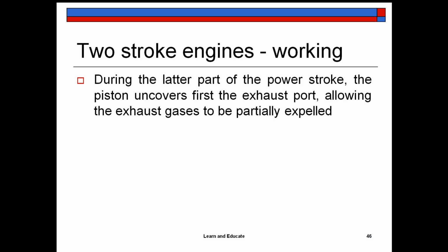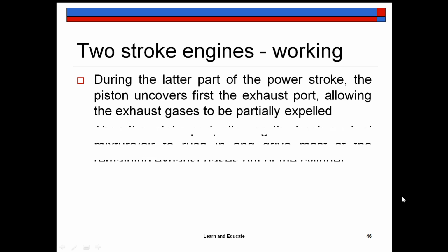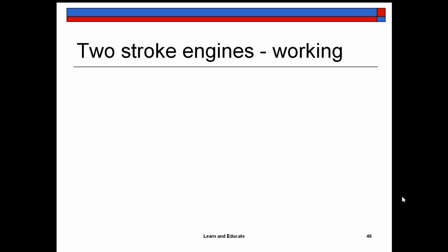So as we have discussed, during the latter part of the power stroke, when the piston is coming down from the top dead center to the bottom dead center, the piston uncovers first the exhaust port, then the transfer port. So there will be a slight amount of time during which both the transfer port as well as the exhaust port will be opened. So there are chances that the fresh charge may get expelled through the exhaust port. That is a disadvantage, and in order to overcome that disadvantage, that deflector is provided.